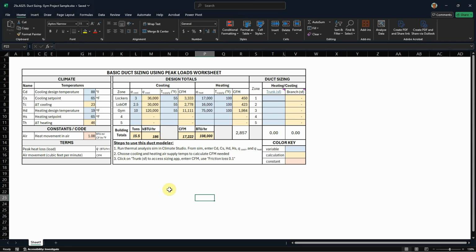the question here is, what's our peak load for heating and cooling? And the one that's the most per zone is going to determine the size of the duct. So in all of our cases right now for these three zones, as far as how we've simulated it, the cooling load is driving the size of the duct. So the last thing we're going to do is go size the duct itself. So I'm going to open up this website.